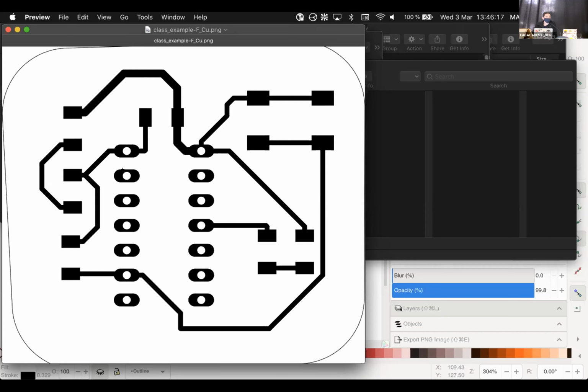Those are through holes that you're going to mill directly with the 1/32 inch end mill. But if you keep it like that on the traces, with the 1/64, it will take out the cover of the holes. You don't need to take it out because you will want to do it all the way. So this one is faster for creating the files and everything, but with the other one you have a little bit more control, let's say.